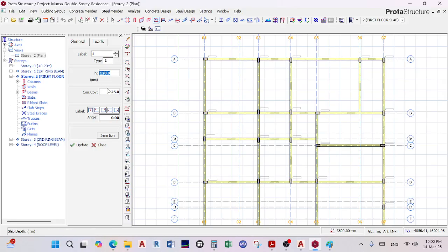And then I'll give it a thickness of maybe 160, right? 25 for a first floor slab is acceptable for me personally. If you like, you can bump it up to 30, meaning if you have 30 at the top, 30 at the bottom, because 60, the meat in the middle and thickness will be 100. But I'll maintain 25 so that it can be 25 there, 25 at the top, and then your concrete spacer blocks will be 25.